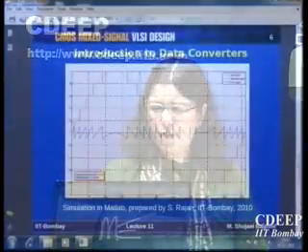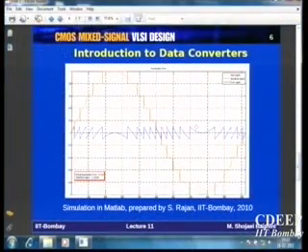If I quantize values before going to digitization, just quantizing values, how much information do I lose from the signal? We already lose some information because of discretization in the time domain, which is sampling. Now we lose more information because we have one more step, which is quantization. So here we have more loss of information compared to switched capacitor circuits.